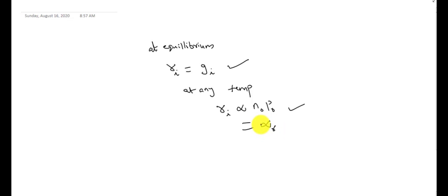So Ri is proportional to N0 P0, that is equal to alpha R into N0 P0, where alpha R is the constant of proportionality that depends upon the mechanism of recombination, direct or indirect, or we can say it is the recombination rate. And Ri is equal to alpha R into N0 P0, and this is the same as alpha R into Ni square. Ni is the intrinsic carrier concentration.